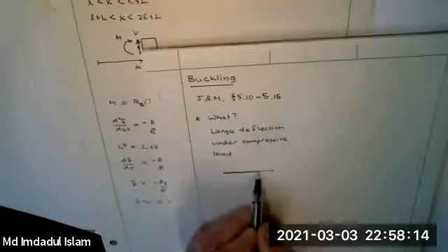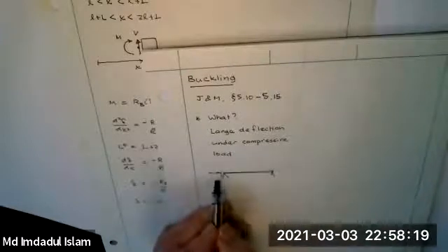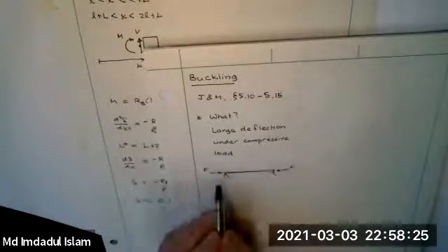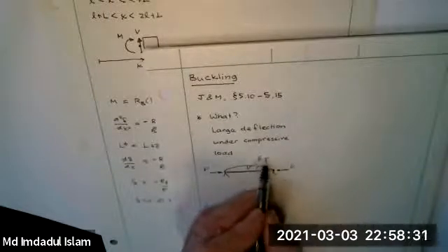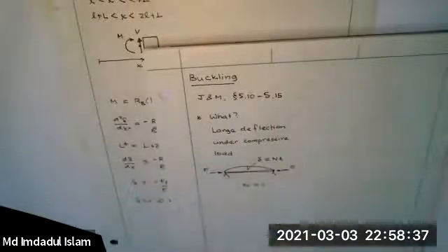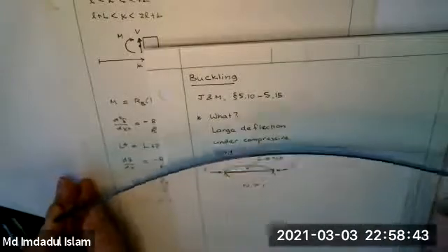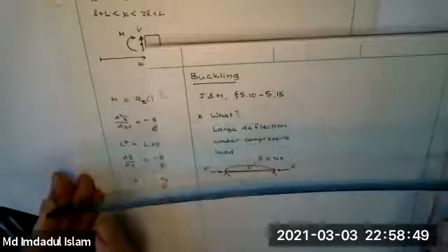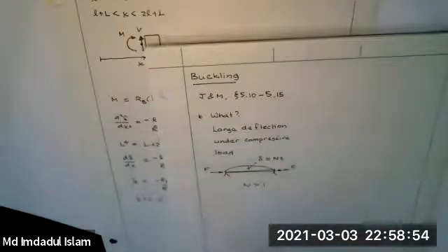Okay, so in situations like this, what I just did with the ruler, the ends were free to rotate in my hand, so it's like it's simply supported. I supplied an equal and opposite force F, and I got a deflected shape like this. When this delta was a significant multiple of the thickness, I don't know if you can see. There we go. That deflection looks to me like an inch. The thickness is a 16th of an inch, so it's 16 times. So these are large deflections.